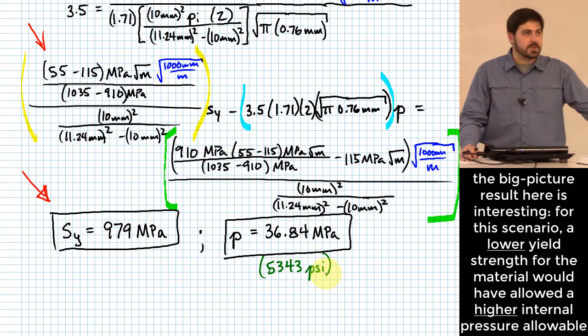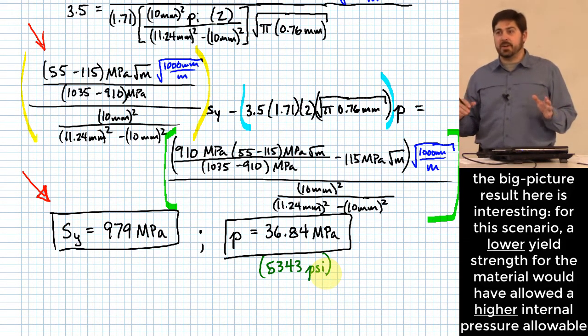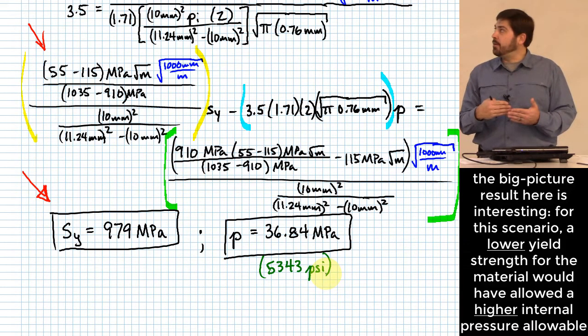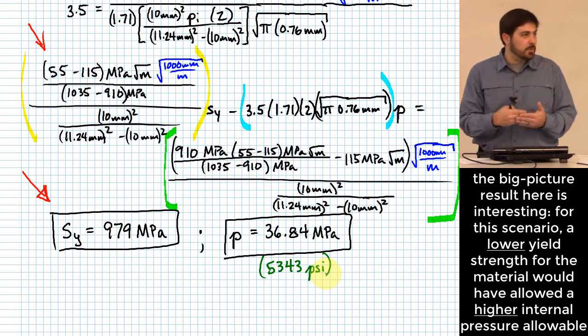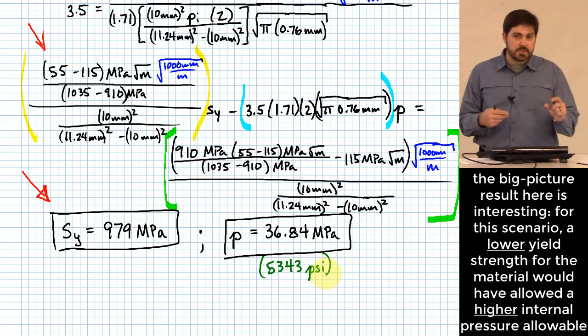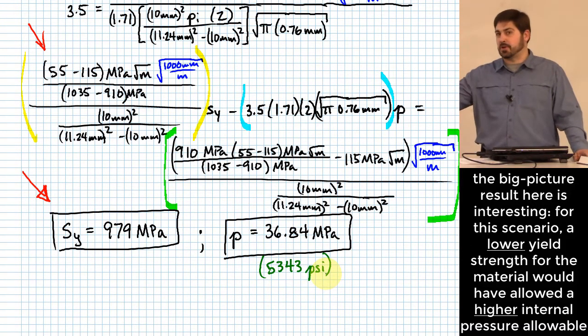Isn't that interesting? So I want us to not miss this big idea here. You can sometimes improve the prospect that a material will withstand the types of load that it needs to withstand by actually reducing the yielding strength, right? And the reason why is you're making it less susceptible to fracture by doing that, less susceptible to cracks propagating through the material. Isn't that interesting?